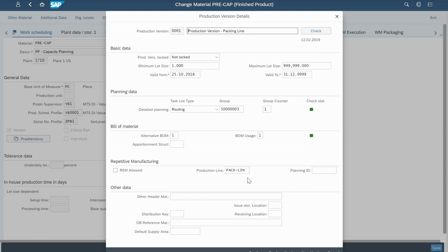Now, the application Schedule Production is there to help you plan the cadence setting work center or the bottleneck. It's unrealistic to try and plan everything in your routing. So the idea is that you plan the pacemaker, the cadence setting work center, the one that is, so to speak, going to beat the drums of how your manufacturing operation runs. Or if you have a production work center that is often overloaded and becomes a bottleneck, then of course that's where you want to level the capacity over a certain horizon.